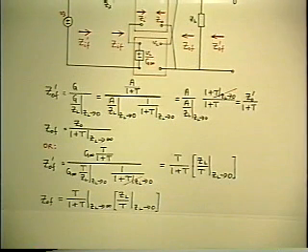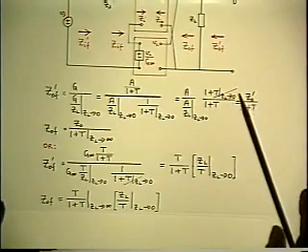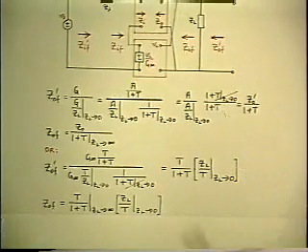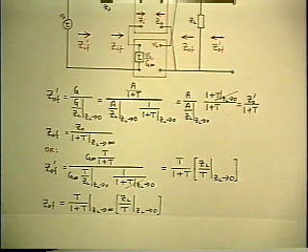Now, you haven't seen that one before, I'm willing to bet. Looks a little mysterious, because it's got this funny limit still in it. But look at how useful that is, because it tells you that the closed loop output impedance of your feedback system is solely a property of its loop gain, and nothing else. That's sort of a revelation, I think.